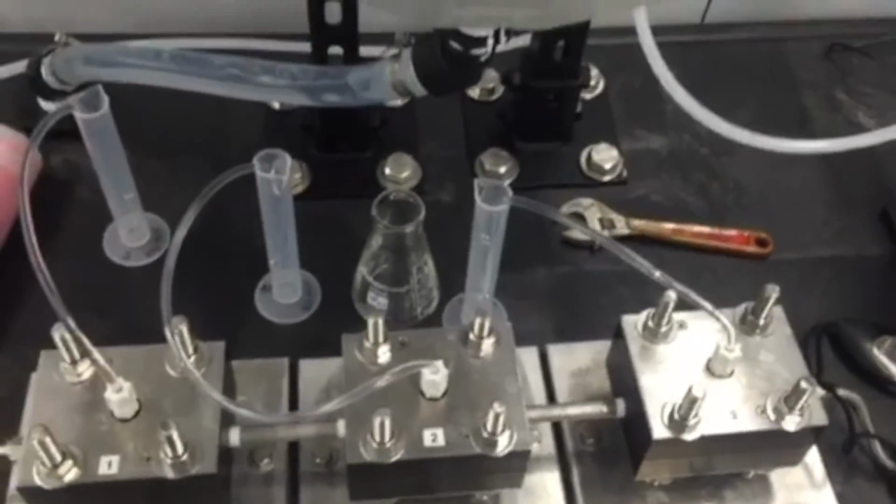Once finished, you can repeat all the same steps. Additionally, you can adjust the pressure to 200 psi and complete the steps again. To test with a concentrated feed solution, create a 1 liter solution with enough NaCl to create a 2,000 parts per million saline feed. Add to the feed tank and allow 10 minutes for the feed to mix. Test using the same operating conditions. You can repeat the same procedure with the BW30 membrane and compare results.